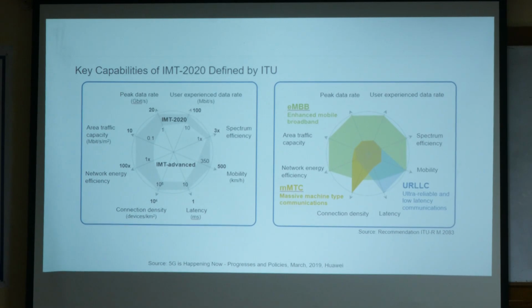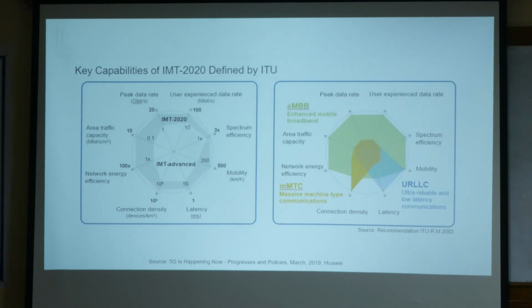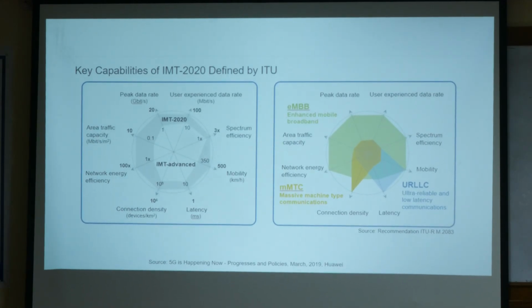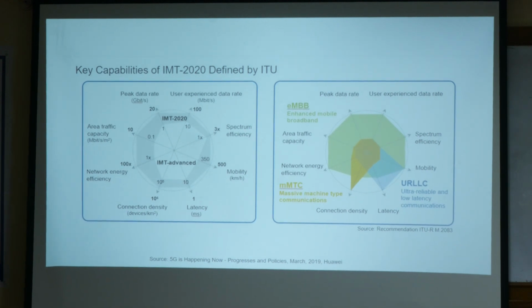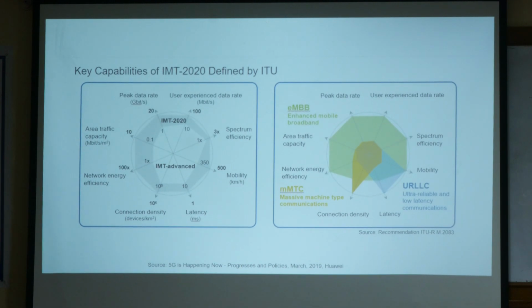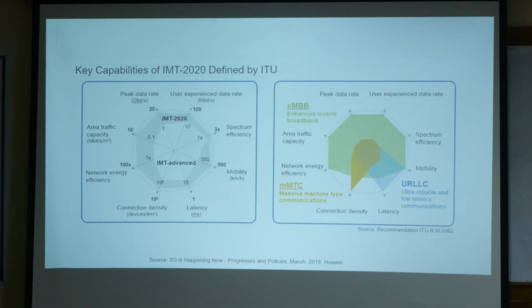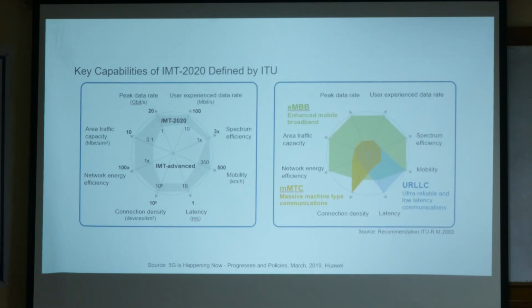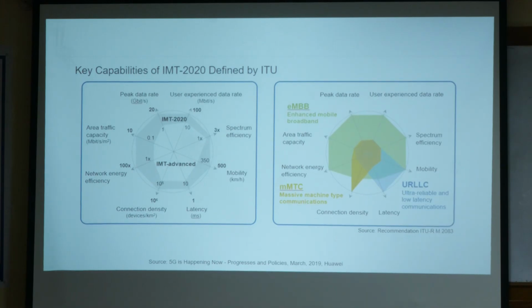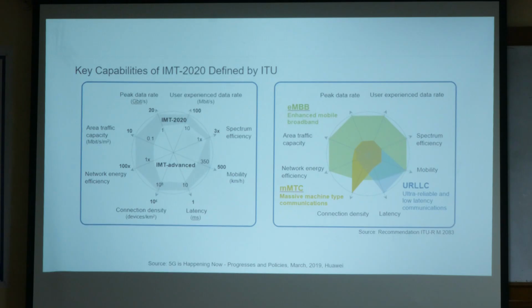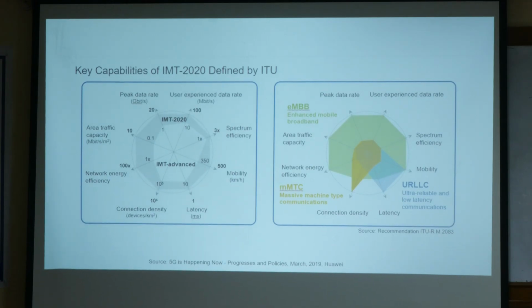So if there is a delay over there, then the second phase robots will do their operation without the parts only, right? So the movement has to be very precise, and they have to execute the jobs at the defined time only. We call these time-sensitive networks. So they have to exactly follow the timings in the network to get the result out. So in that case, you cannot play with the latencies over there.